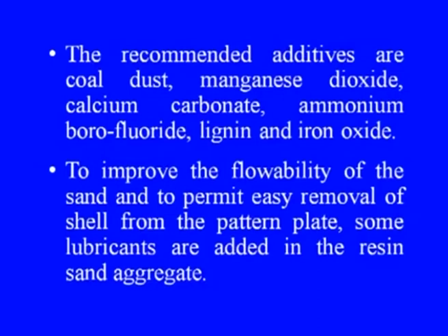Now, let us look into the functions of additives. Additives may be added to the sand aggregate to further enhance the surface finish of the casting. It also improves the strength of the mold and develops the resistance to thermal cracking and distortion. The recommended additives are coal dust, manganese dioxide, calcium carbonate, ammonium borofluoride, lignin and iron oxide.